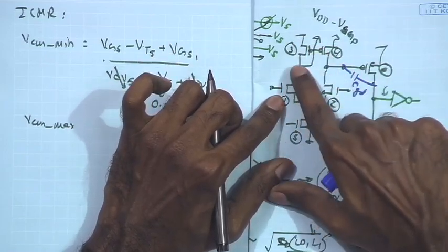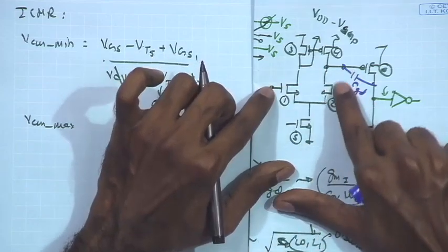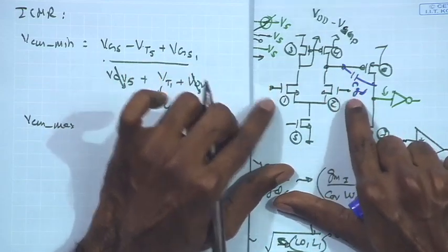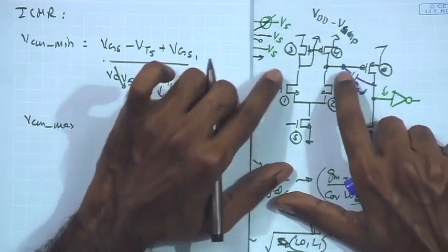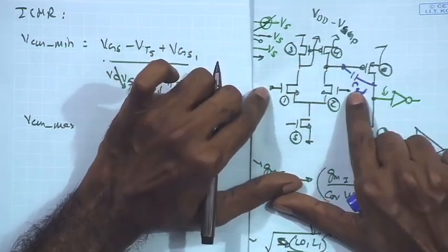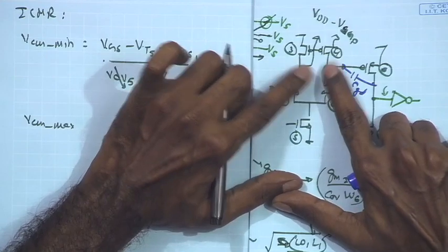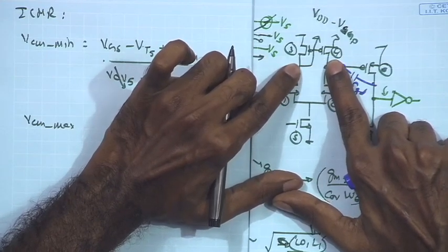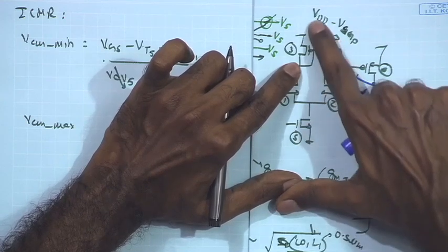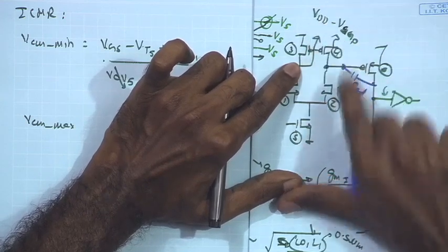And remember for this differential amplifier with current mirror load, if you are increasing this input gate potential, if I assume that both of them are close together, the output potential over here will be close to the diode connected voltage over here, VDD minus VSG.